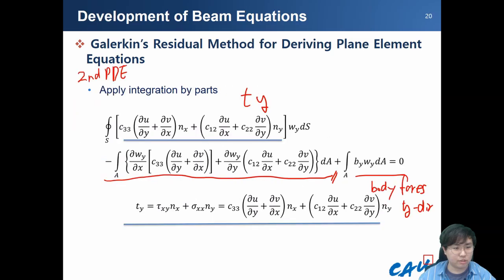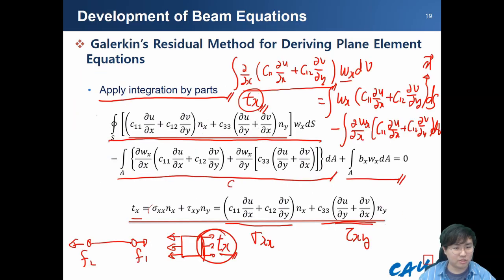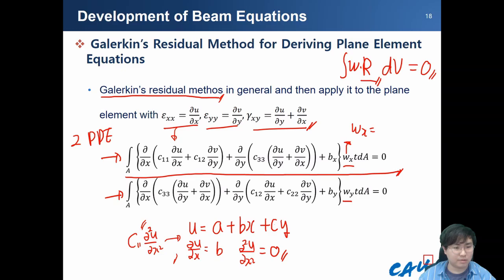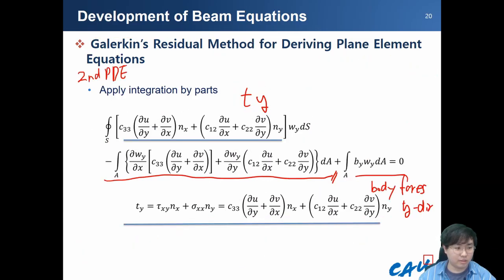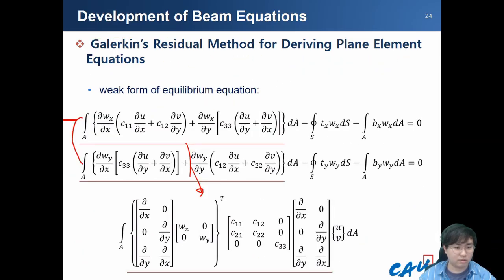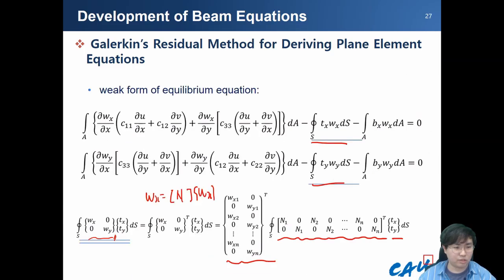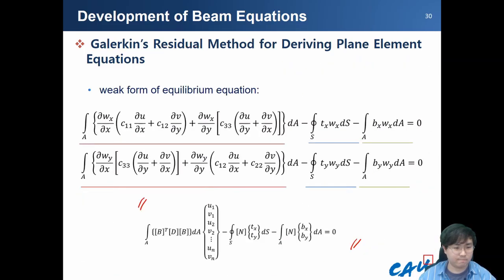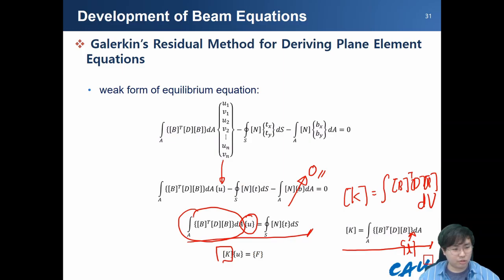We should actually consider the thickness, but I just assumed that the thickness equals 1. Here, for the local stiffness matrix, we should consider the thickness. I neglected the thickness in the 2D cases, so just think of the thickness as already equal to 1. But if I assume the thickness is 0.5, then at that time you should consider the thickness here.